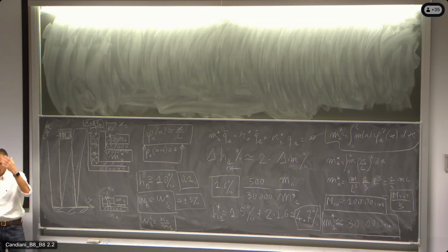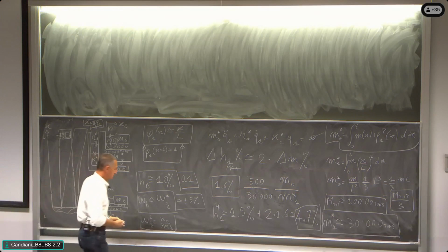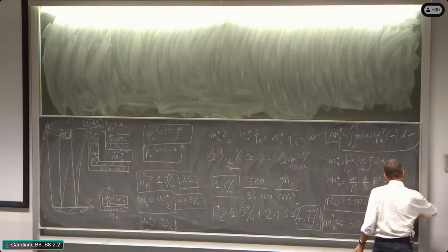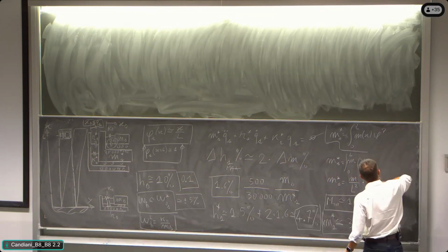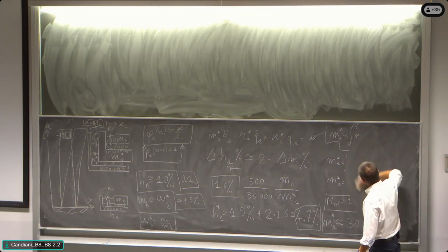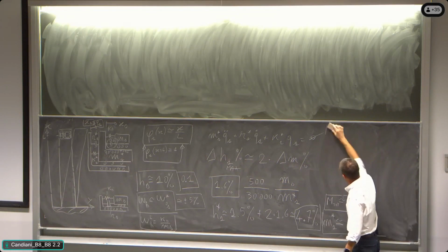It is extremely light, and it is very sensitive to the wind effect, both in torsional motion as well as in the bending motion. So it is like a mast. The best is that you look at the Torre Piloti Genova on the web. It is very light, and it is very sensitive to the wind effects.